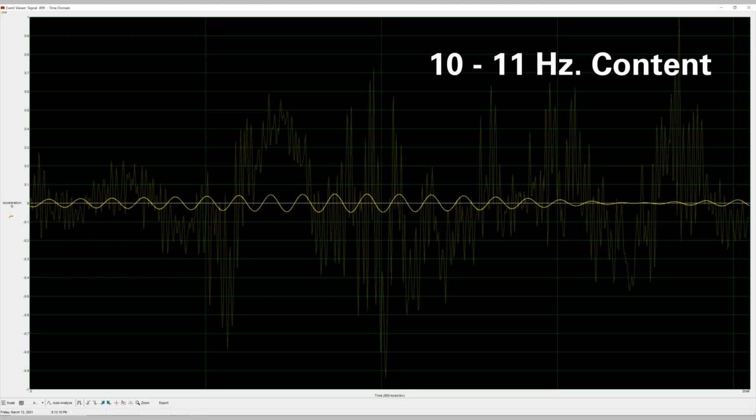as I apply that filtering and focus in those areas of a frequency range, very tight bands, that's the signal or the contribution, in this example here, 10 to 11 hertz, that, believe it or not, is in here. It's in this noisy signal in the background. And we can dissect that. And that's what the Fourier transform basically does. I only showed 1 to 11 hertz, but it does that across the whole frequency range that we're interested in when we do these types of measurements, okay?